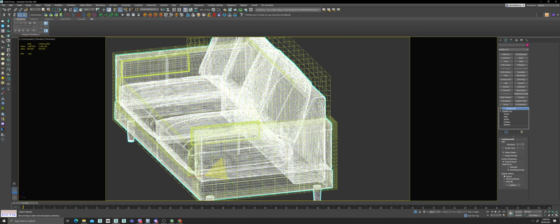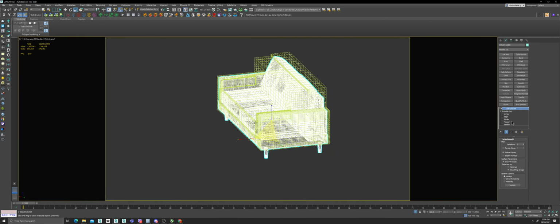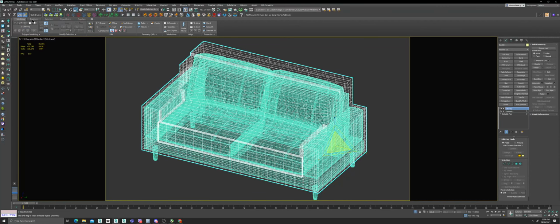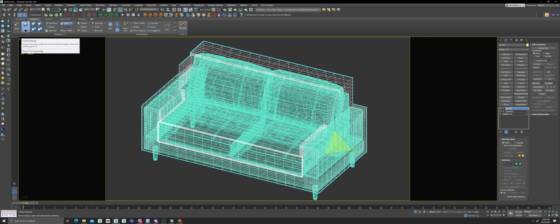And the tool to use to do that is the command Conform. Let's add an edit poly on our original mesh. So we are going to conform this mesh to our original mesh. To do that, you go to your modeling ribbon on top. Select any. Go to Freeform. And then you're going to use the conform brush. This one.